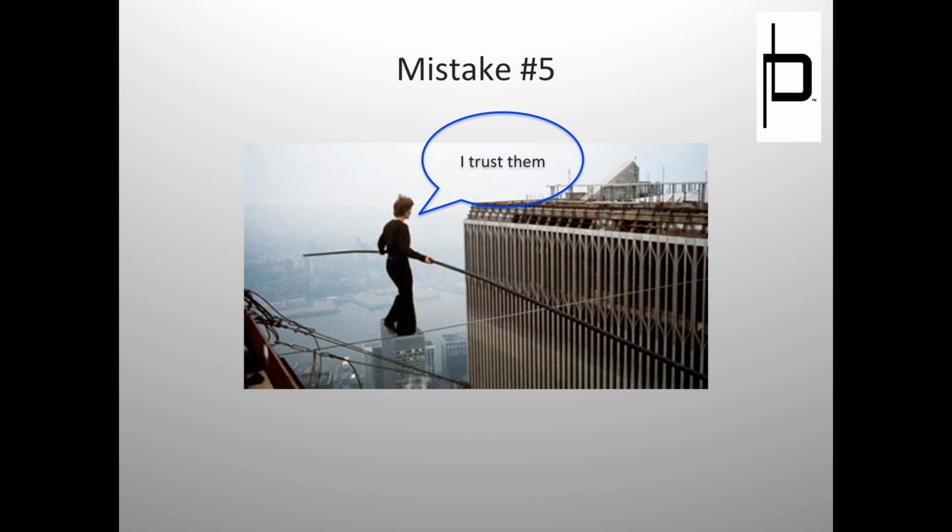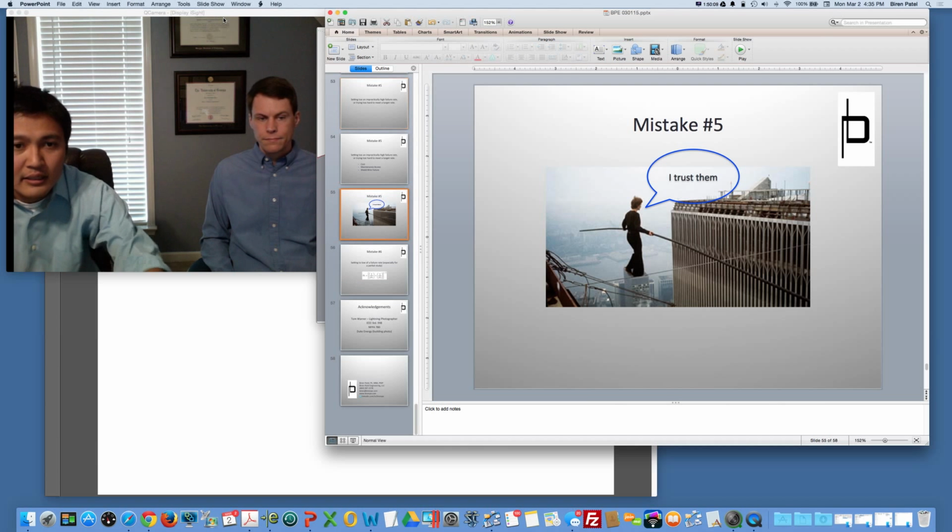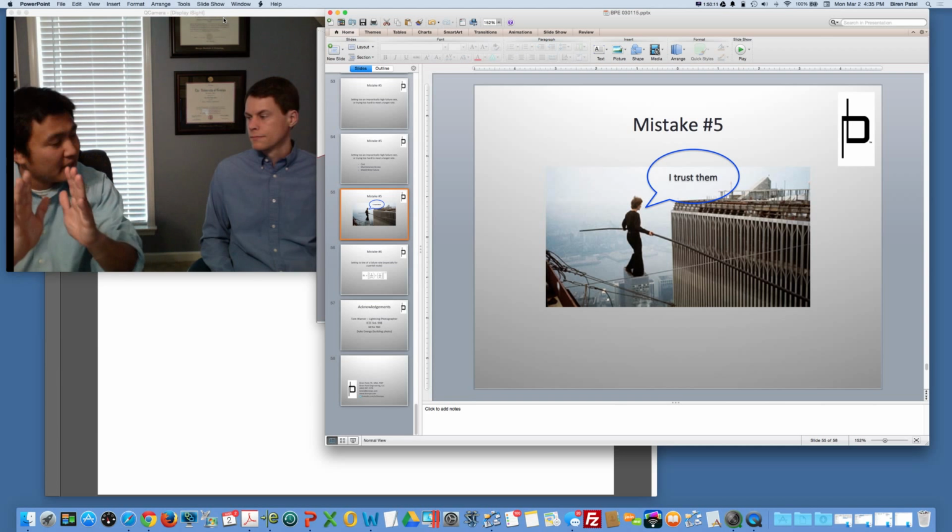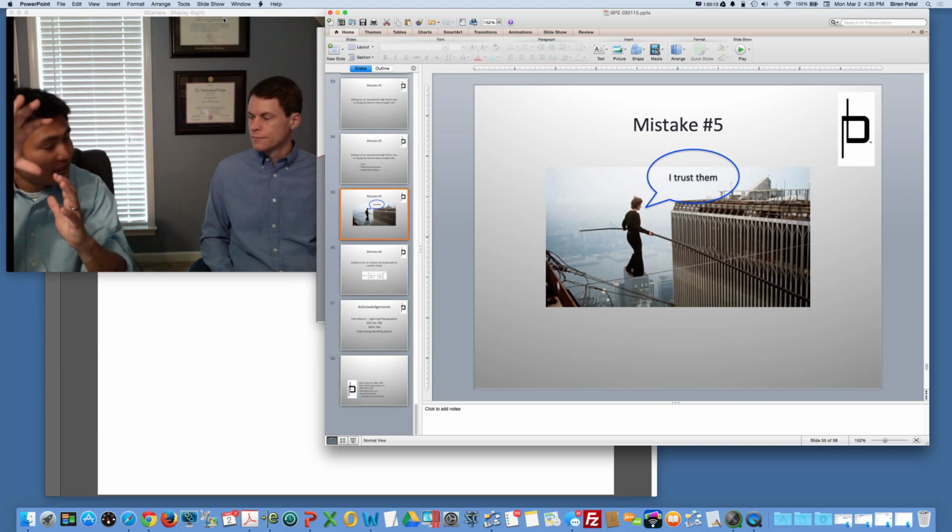Maybe they do, but personally, I don't. We can't always say that the shield wires are going to fail or not going to fail. And so the important thing there is when you design your shielding. If you remember, we were talking about the combination systems. We were talking about how when you have two wires parallel, as long as you're supporting that sphere, it's very easy to protect your whole substation that way.